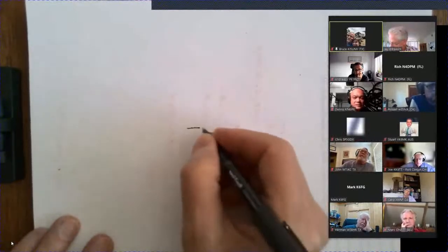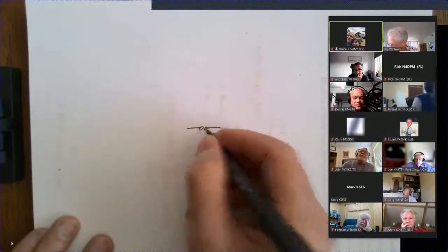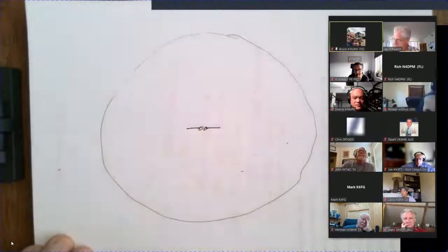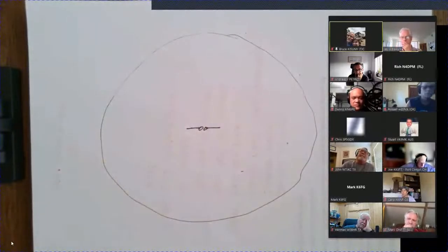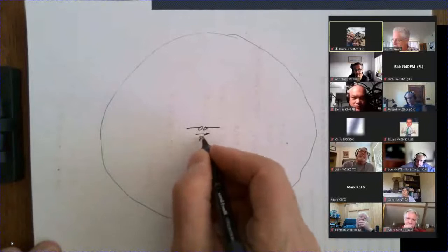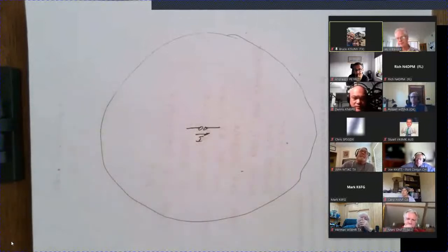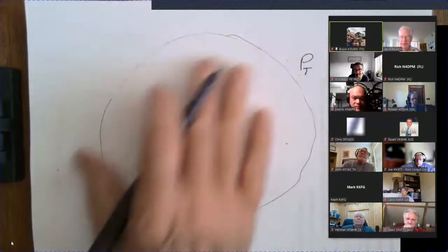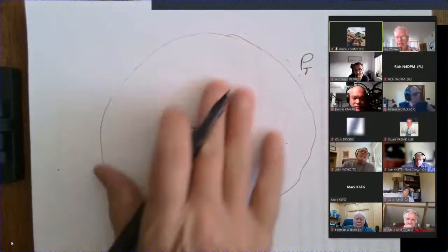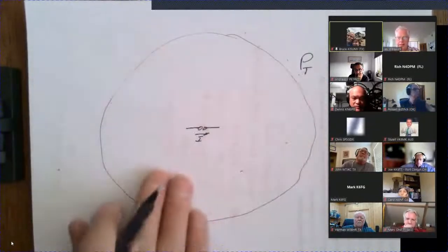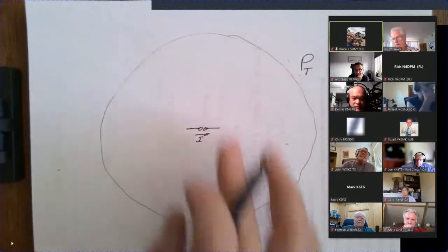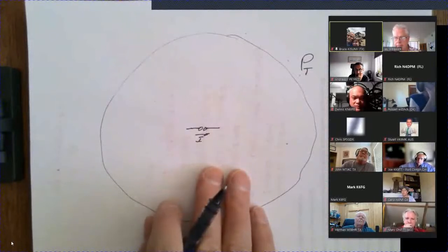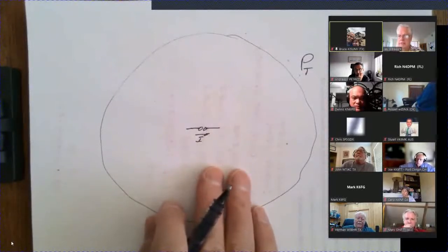So we've got our little antenna here. This is our little dipole and our transmitter in the middle here. And we have around it this sphere that we talked about before. We put some current in here. We get some current flowing in the antenna at the feed point. We can measure the total power that's crossing this sphere. That's how much power is radiating out of here. That's how much energy per second is flowing out into space. It never comes back.